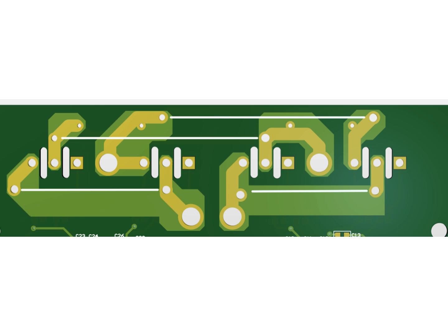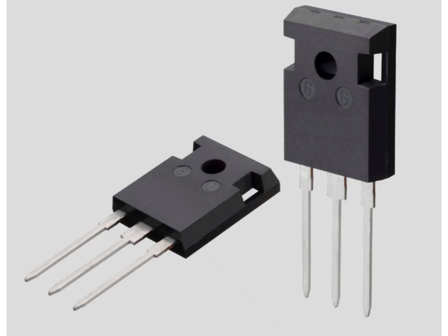This design practice is especially important in motor drives, inverters, EV chargers, solar inverters, and welding power supplies, where high voltage, fast switching, and harsh environments are expected over the product lifetime. In this design, the IGBTs are placed on the bottom side of the PCB, while their leads are soldered on the top side.